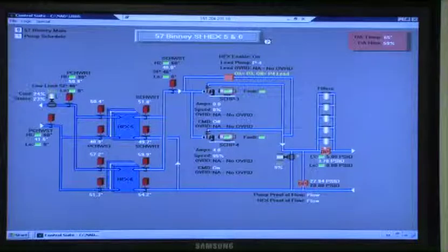The drives have a minimum speed on them, but it is redundancy. It's not there to maintain a specific flow. The ABB drives have a minimum when we get a start command, they go to their minimum flow. Once we get proof, then it starts to modulate up and down. Like Steve said, if the DP drops low, your bypass valve is going to modulate accordingly to try to get your pressure up in the system. If you're talking about a failure, that's why you have redundancy, 2 drives, 2 pumps. You'd go to here, command the other one off, if you think there's a problem with the drives.